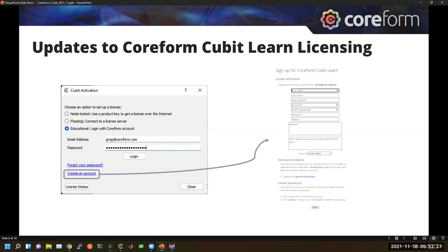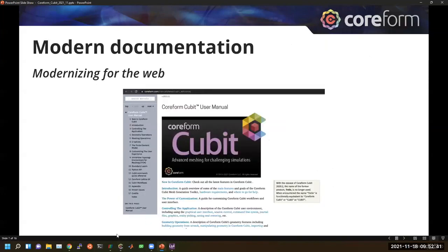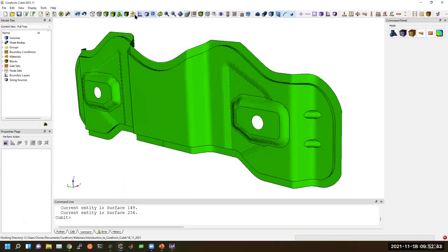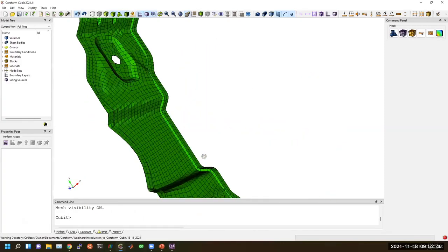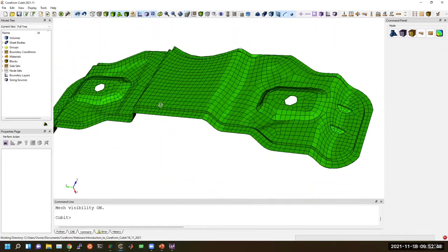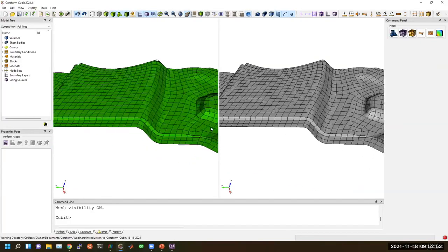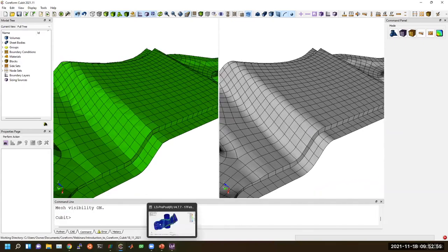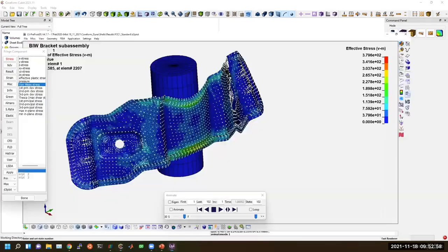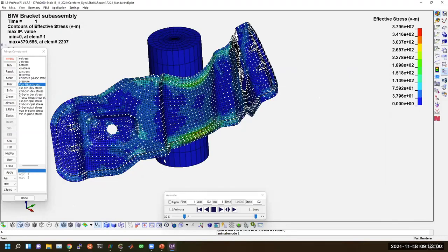Yep. So, okay, we got one more question from Clint. Can you mesh a shell in Cubit and fit a U-Spline to it to use in LS-DYNA? Yeah, and actually, that's what we showed earlier. Building a surface mesh on this shell and building a U-Spline on it. I think I've already built this U-Spline. And then exporting out to an LS-DYNA file. And so it comes through as a .k.